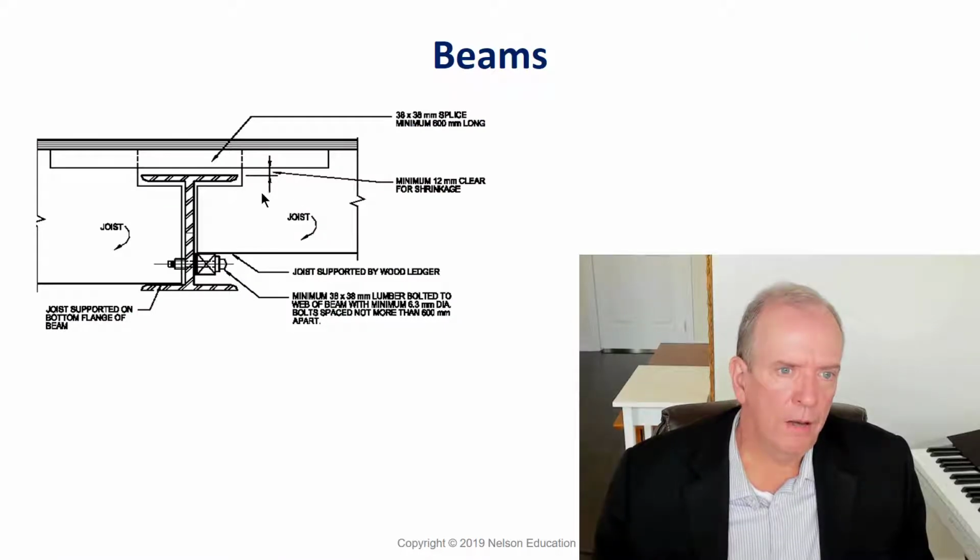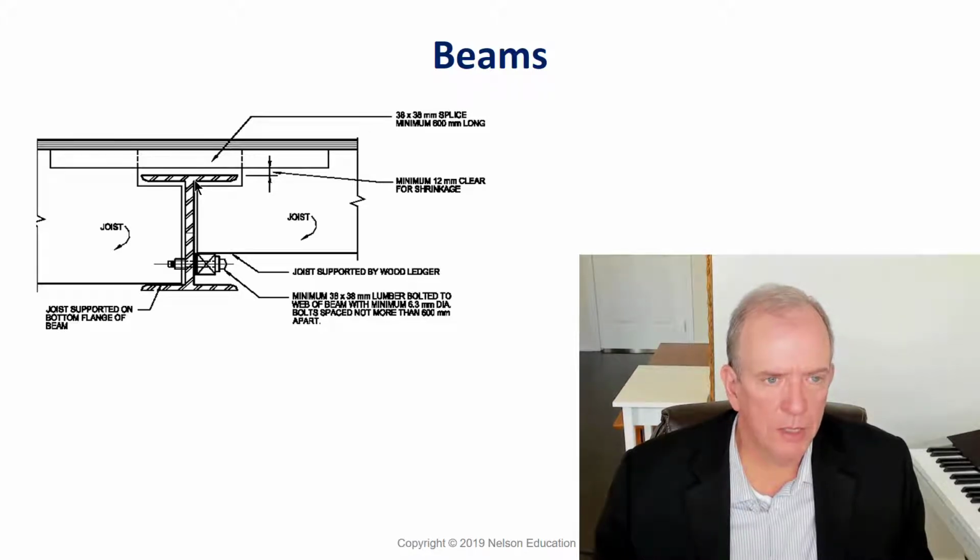Here we have a steel beam, and you've got joists, and you notice the joists are notched on the top. You can notch joists on the top, but there are limits, all right? So they notched it on the top and put a filler piece across, nailed it to the side, so that the subfloor would be supported. That's the hatching, and that's a subfloor up above. And you notice they left a space there.